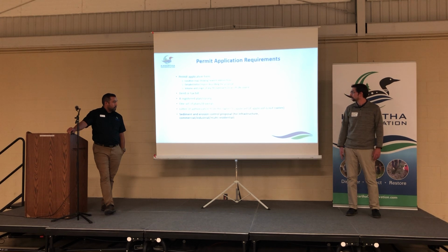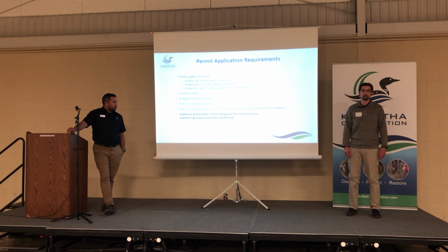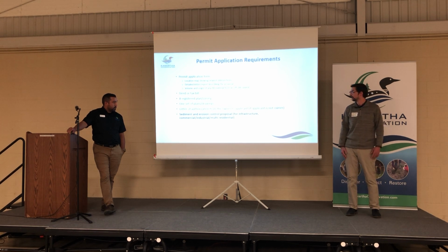For larger infrastructure projects, commercial, industrial, and multi-residential, we do require an erosion and sediment control plan to be submitted at the time of the permit application. For more minor works, it's not necessarily a requirement, but we do appreciate when people include that with their permit application.